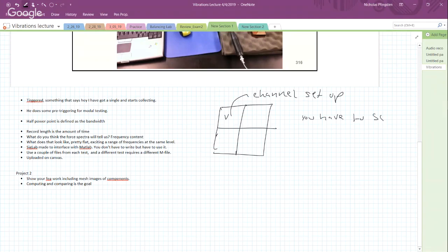It's nothing to do with calibration. So let's say we're trying to measure a 10 volt signal and our input range is set plus or minus 5 volts. What's going to happen? There's a word that we use. Quantization. Really?